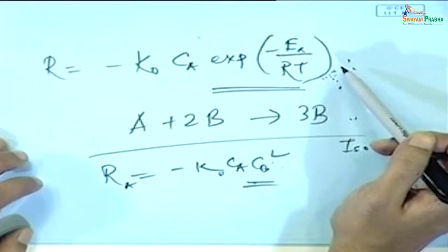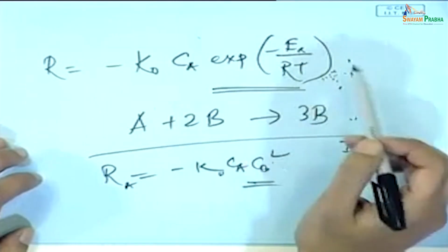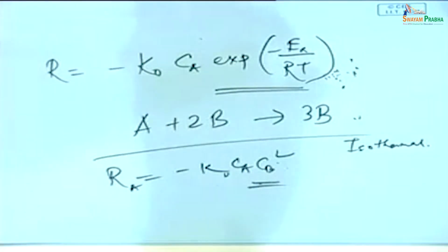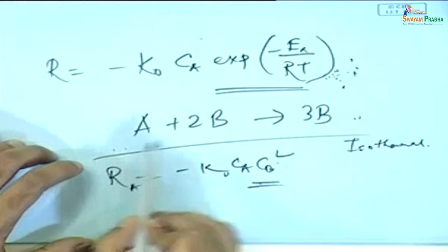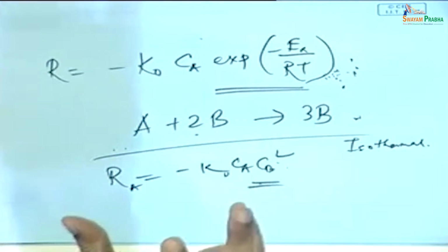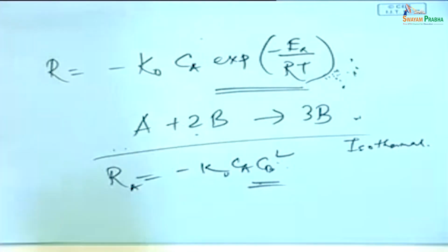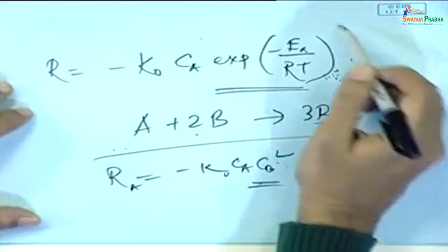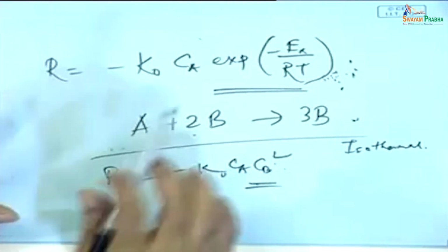So at the same point in time and two different points in space, two different temperatures coexist. Or if you're talking about A plus 2B giving 3B, two different values of B coexist, two different amounts coexist, but these are supposed to be continuously stirred, completely mixed reactors. So despite all the mixing, this is allowed because of the form of the equations, and this is multiplicity.